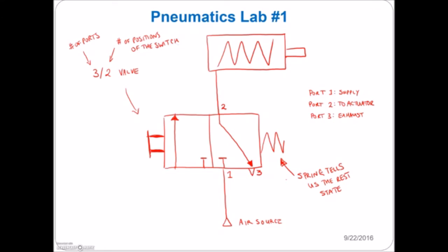Okay, we said that this guy was normally closed, so it's a little bit backwards, in that everything electrically is kind of backwards from PLCs or from pneumatics. So normally we would think of a normally closed contact like this, meaning that current could go through to our load. In this case, when they say normally closed, it's acting more like a normally open contact, electrically speaking, meaning that it is normally closed to the passage of air.